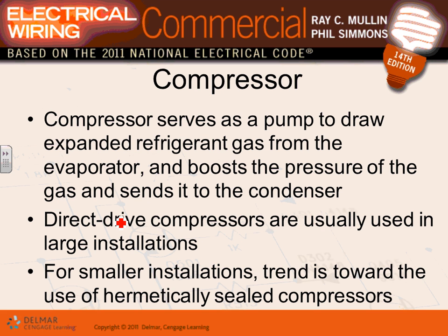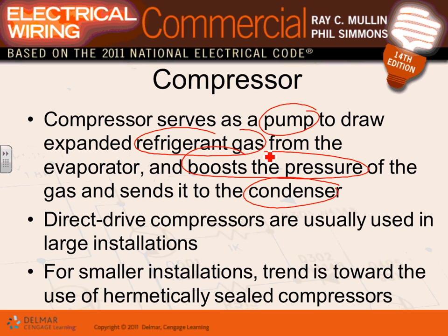The compressor has two functions. It works like a pump. It pulls that refrigerant gas, low pressure gas, from the evaporator into the compressor, as well as compresses it down into high pressure gas. It sends it to the condenser and boosts the pressure, so it becomes high pressure gas to facilitate the operation of removing the heat from it.